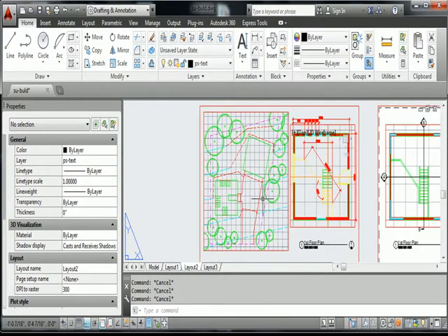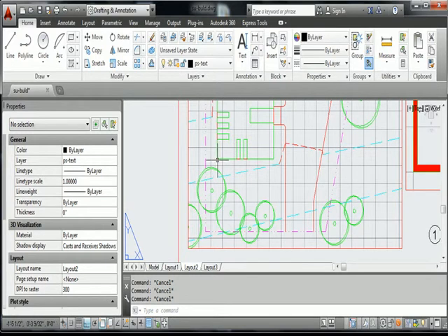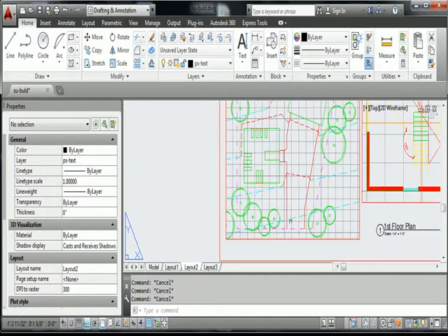This guy right here, if you could refer back to the dimension of this thing, you're going to align a text along the property line and say PL 75 feet 0 inches, PL 51 foot 0 inches, and such, to label the dimension of the property line. And I guess we could put a dimension line just like what's on the wall of how far away the building is on the property and the like.